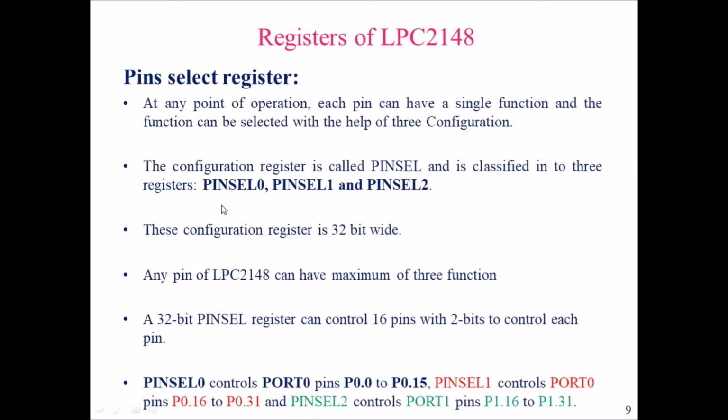Any pin of LPC2148 can have a maximum of three functions, and one of them is general purpose input output. So we have a maximum of three functions that can be associated with the LPC2148's 64 pins. A 32-bit pin select register can control 16 pins, with 2 bits to control each pin.